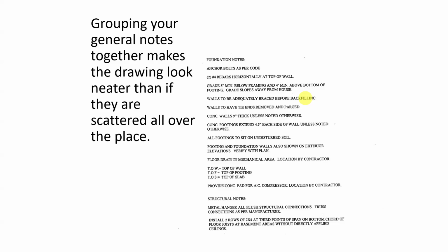Remember I talked about last lecture that footings need to sit on undisturbed soil, or it has to be professionally compacted to match what the undisturbed soil is. So I have a note about that.